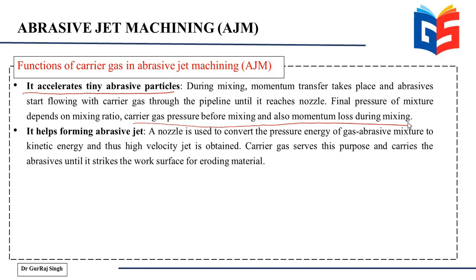Then it helps form the abrasive jet. A nozzle is used to convert the pressure energy of the gas abrasive mixture to kinetic energy, and thus a high velocity jet is obtained. So it basically serves this purpose and carries the abrasives until it strikes the work surface for eroding the material.